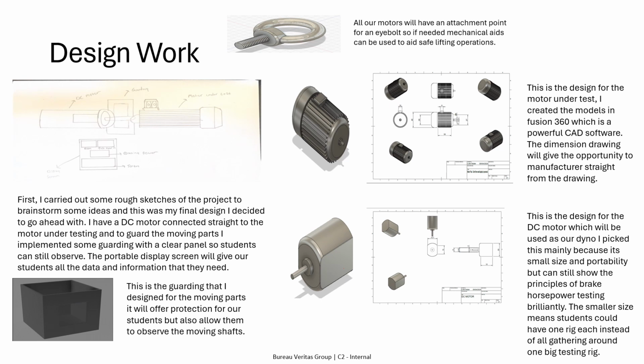So if you look at the bottom left, you will see the guarding that I have designed. This is to protect our students from the moving shafts. And if you look at the top, you will see the eye bolts. So all of our motors will have an attachment point for an eye bolt. So if needed, mechanical aids can be used to aid safe lifting operations.